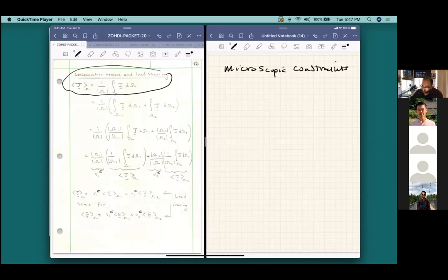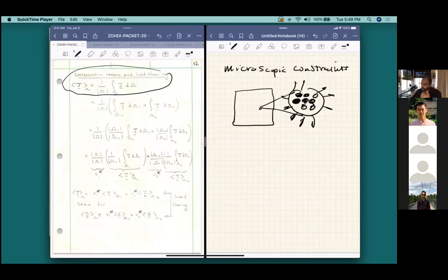So the problem, however, in all of these kinds of analyses is that when you look at a piece of material, so let's suppose we look under the microscope at some kind of a structure, anytime we start to load it up, the material has different load sharing capabilities. That means the particles take some part of the load, and that load could be a thermal load, elastic load, electrical load, and the matrix takes on a load in response.